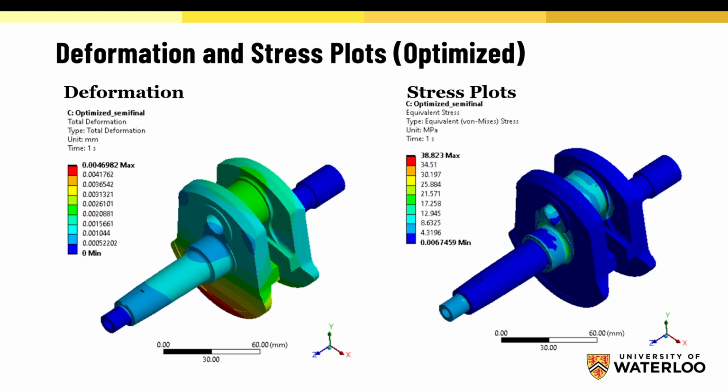And before you share results with someone, make sure you can defend your position. So given the time constraints, we thought that ignoring convection around the enclosure would be reasonable because we don't have information about that. And we wanted to simulate the worst case scenario if there was no airflow. So yes, our simulation is overshooting the temperature a little bit and we're not truly accurate, but it's a worst case scenario. That's a good justifiable reason.